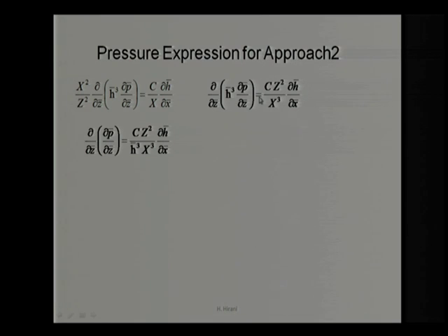For our case, for present assumptions, we can take it out without really differentiating with respect to z bar, because h is not a function of z. So we rearrange this term. Here the h bar comes, which is only a function of x. Now, we can integrate it, as this whole term does not depend on the z, and this also does not depend on the z.